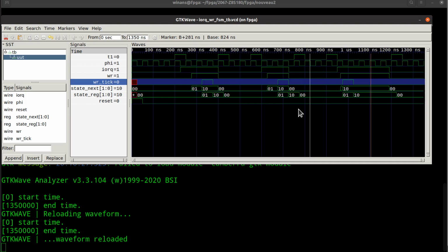So what we got in conclusion here is the write signal will work for an I/O operation, even if the write signal is asserted by the CPU after the worst case timing is true. It would still work for us, okay? Normally, it'll look more like this, but it won't have the extra timing pulses. So the point is it'll go high after T2 during TW, and it'll give us the ability to see this falling edge on TW and latch our data right there.